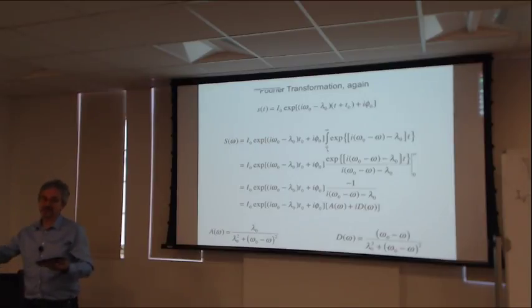So the filters had to be wider than we actually wanted them to be to avoid these artifacts. These days, one has digital filters that are very powerful. So the physical filters tend to be set fairly wide. You record the data, and then the digital filter is applied to that data to give nice clean cutoffs that avoid folding in the extra noise left over by the physical filters.